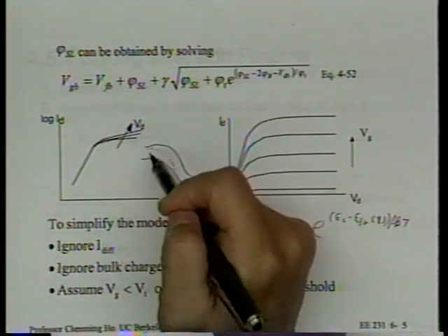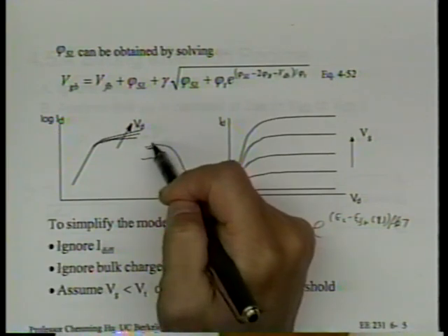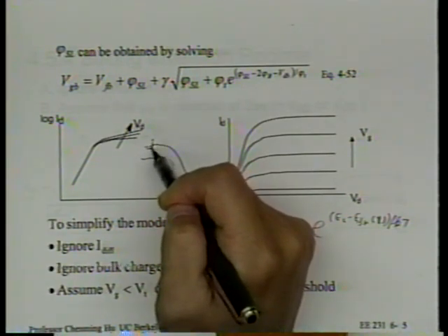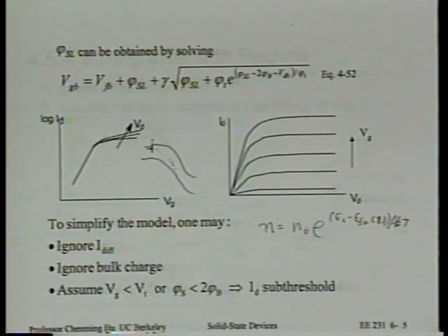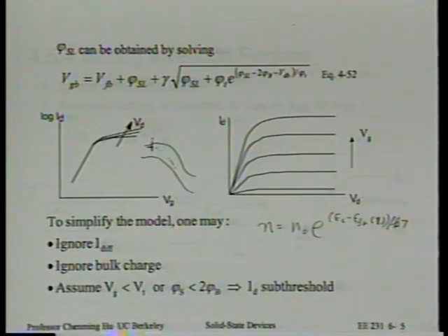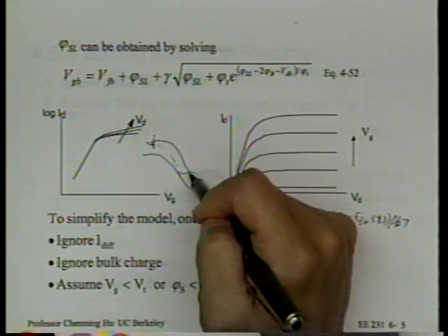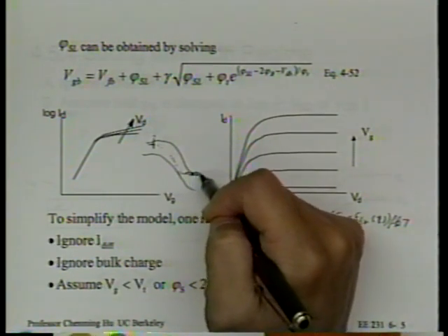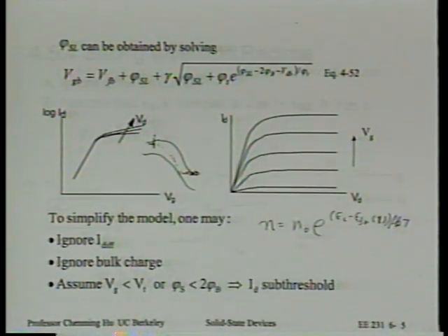But at these two ends, it's very useful, because at these two ends we happen to know what the quasi-Fermi level is. It has to be equal to that, just from this argument, they're communicating with that. And at the drain end, no matter what, we're going to go back to that, because it's communicating very closely with that. That we do know. In the middle, we don't know what the quasi-Fermi level is, so we don't think about it. All right? Okay.